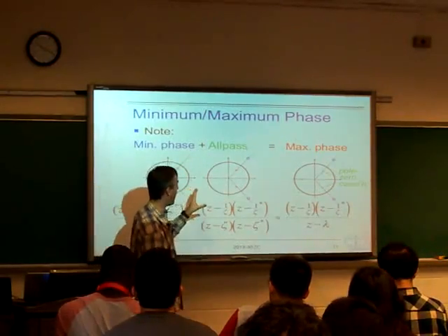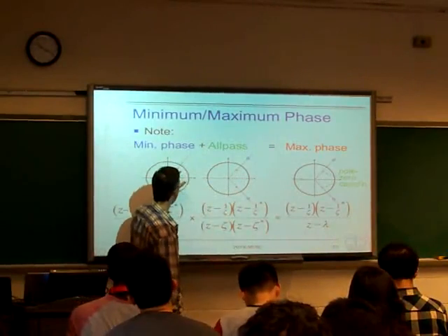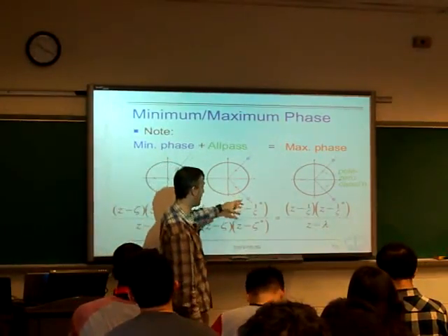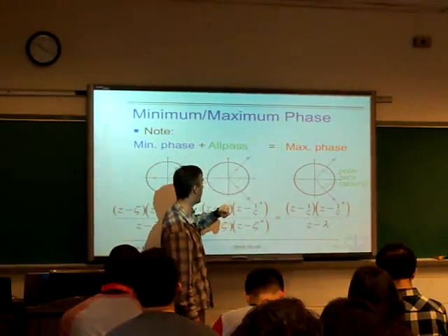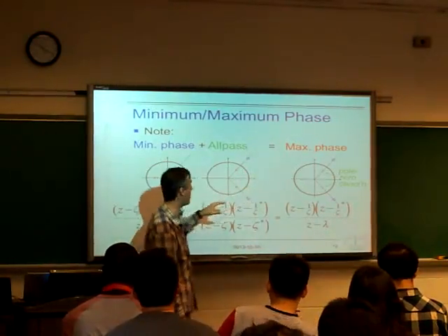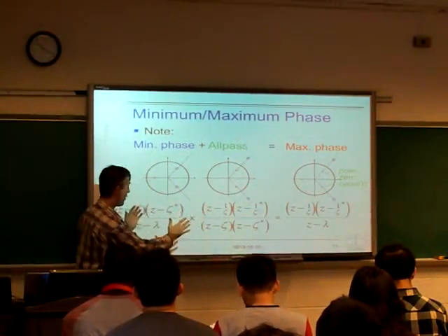We could then take that output and put it into an all-pass filter like this, that has poles exactly where these 2 zeros were, and then also, because of the reciprocal structure of an all-pass filter, we'll have zeros at these reciprocal locations. Putting a signal through both of these would be the same as putting a signal through the product of these two transfer functions.